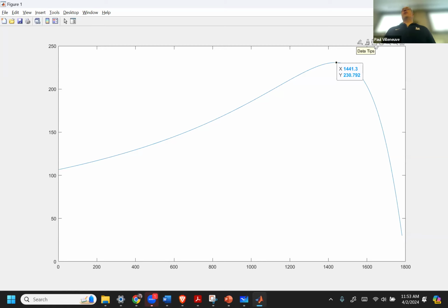Why isn't that 228, 227.8, and a slip of 0.19, whatever? That's because the calculations we're doing in MATLAB are exact. Remember, I had to make some approximations about XM being much, much greater than X1 and R1. This is doing the brute force exact calculation.